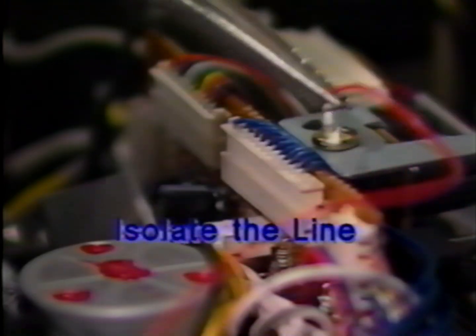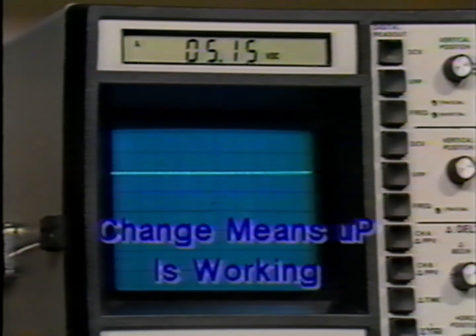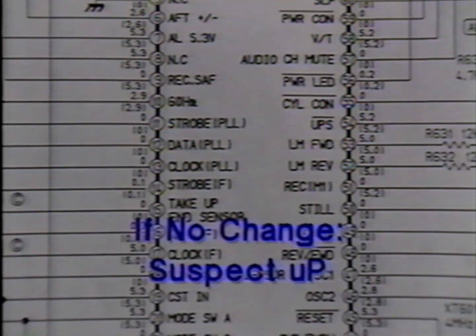If an output line is stuck high or low, lift it from the microprocessor pin and monitor that pin. If the output signal on the pin changes, the problem is likely to be in the motor interface circuit, not the microprocessor. If the lifted line does not change, suspect the microprocessor.